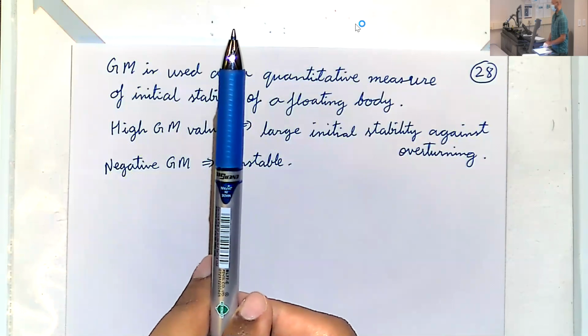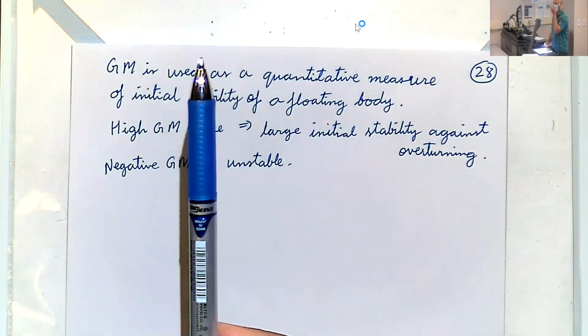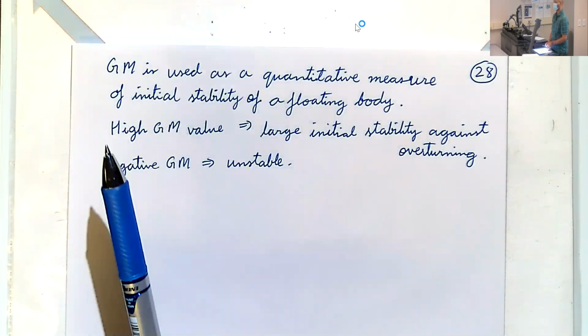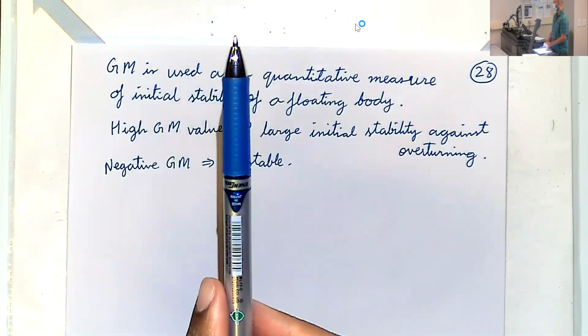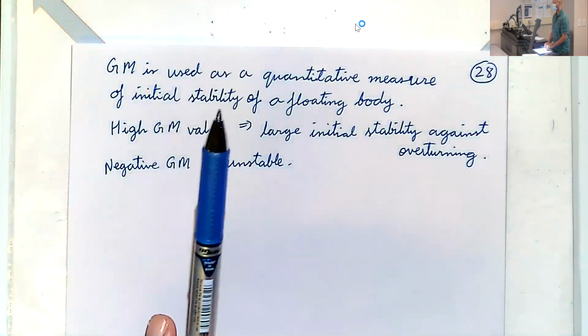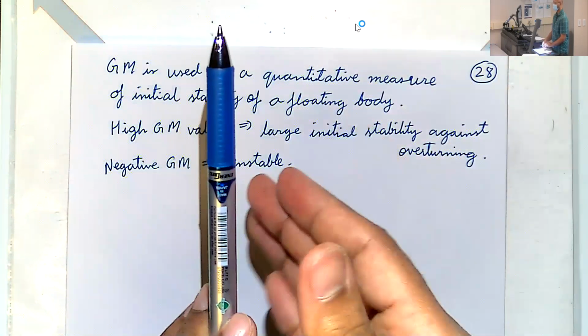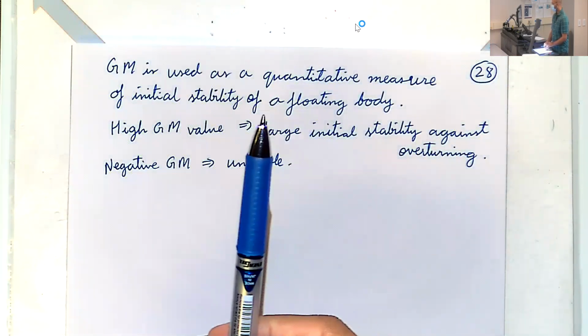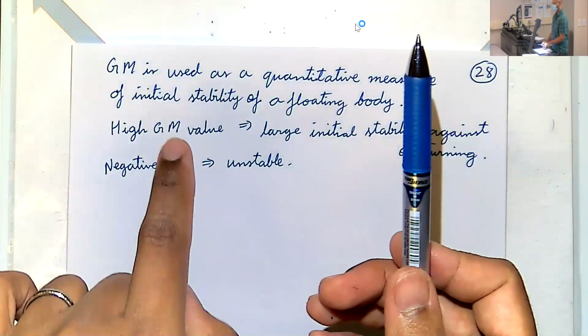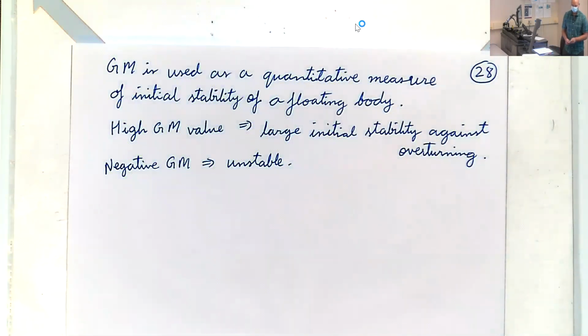So think about the shape of a cruise ship versus a cargo ship. A cargo ship has a very, very large GM, okay? The reason is you want all your containers that are stacked on top to be very stable. You don't care that the waves are hitting you. And the way the hull is designed influences that. We'll see exactly how.